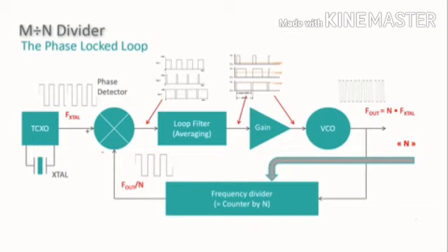And when the VCO runs more slowly than the crystal oscillator, the phase detector senses the change and produces a duty cycle greater than 50%, and that speeds up the VCO. And once again, the two signals stay exactly 90 degrees out of phase. For a lot of PLL designs, this makes a lot more sense than a true bipolar design with 0 phase shift. The loop filter and the gain block smooth the pulse train to create an average DC level.